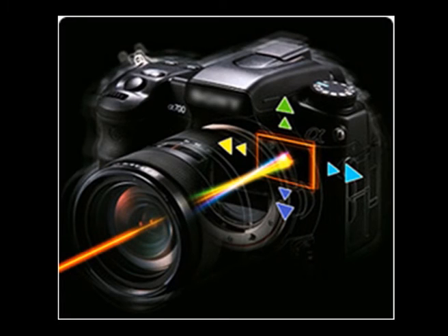Next is the sensor shift image stabilization. In this, there is a sensor in the camera body itself which senses the movement and it moves the sensor, that is your CCD or CMOS. By doing this, you do not need a stabilization system with every lens.